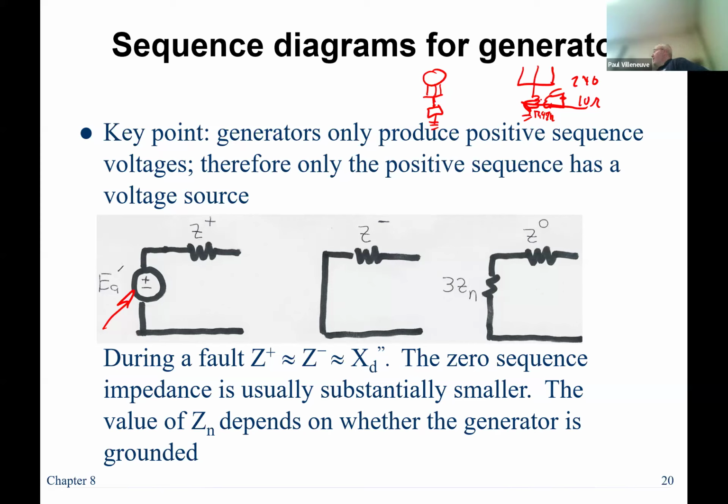So if you were to go to a generating facility, a lot of times what you see is one of those pole-mounted transformers. It's gray and it looks like a trash can. Those will actually be located out by the generators, and they'll step that resistor up, which has to have some power dissipation. So maybe it's 500 watt or something like that capable, but it actually is going to be stepped up to a much higher voltage. It's not often that you see a resistor directly in the generator, unless it's a low voltage generator. Then it's a little bit different.